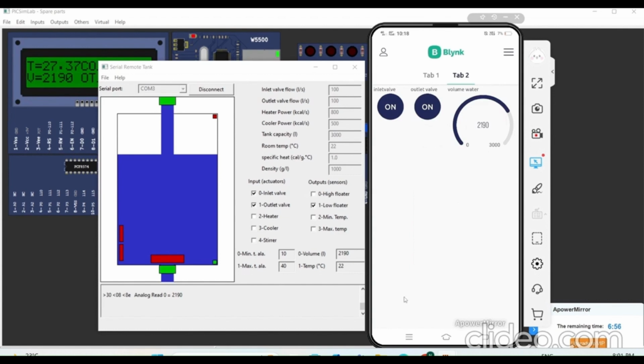Users can remotely operate the heater and the cooler using Blynk buttons from anywhere in the world. Additionally, a smart threshold mechanism ensures safety and energy efficiency. If the temperature crosses 35 degrees Celsius, the heater automatically switches off and a clear notification is displayed both on the virtual terminal and the CLCD, preventing overheating and saving power.